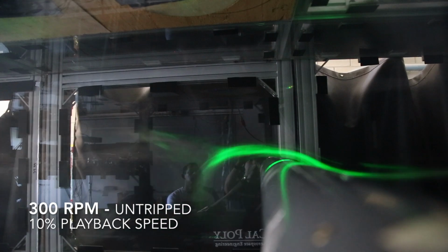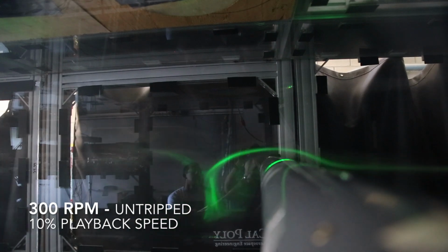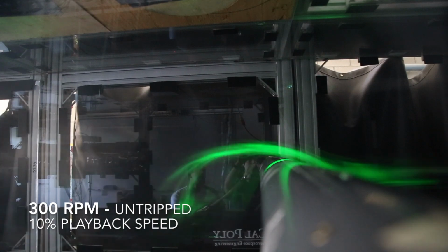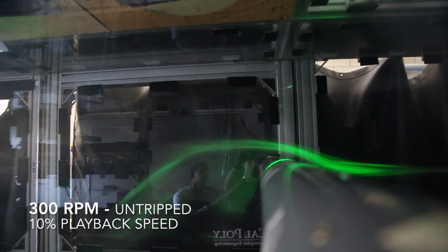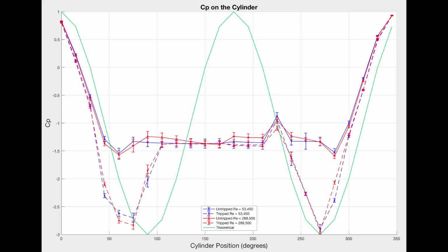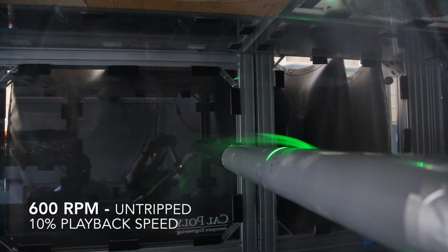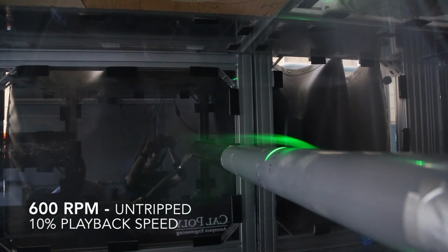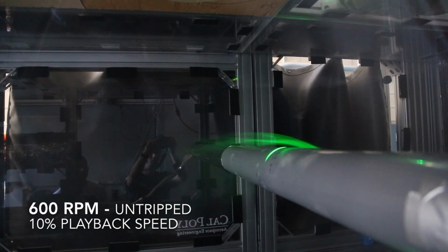This separation occurs because the pressure is increasing in the flow direction, creating an adverse pressure gradient. The fluid particles fail to move against the increasing pressure, and boundary layer separation occurs. It is clear that the flow has become disconnected past this point because the standard deviation of the coefficient of pressure is very high. This implies that there is a large variation in pressure, which is commonly caused by vortices that form as the free shear layer due to the boundary layer separation rolls into a discrete vortex and is shed from the surface.